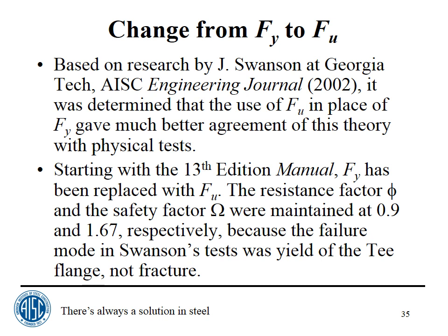One change that took place between the 3rd edition LRFD and the 9th edition ASD, when they were combined into the 13th edition, ASD LRFD, was that F sub y in the prying equations was changed to F sub u. Based on research by Jim Swanson, who was at Georgia Tech at the time, now at the University of Cincinnati, in a paper published in the Engineering Journal in 2002, it was determined that the use of F sub u in place of F sub y gave much better agreement of this theory with physical tests. So starting with the 13th edition manual, F sub y has been replaced by F sub u.